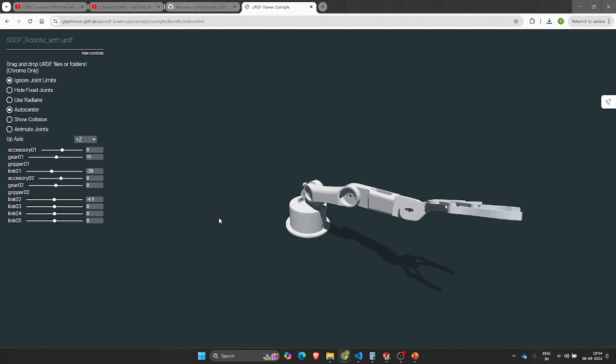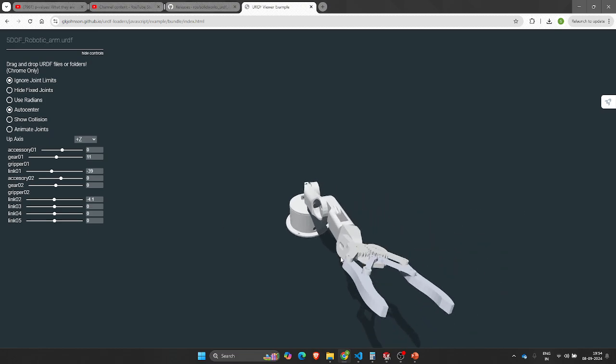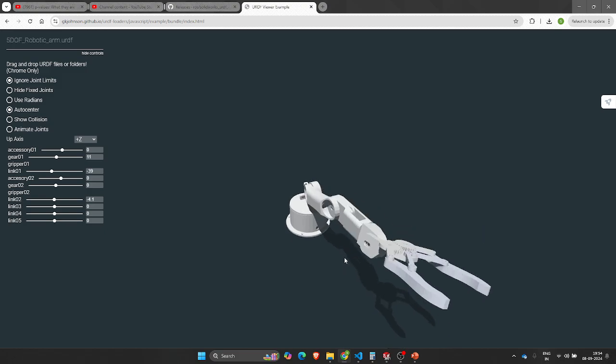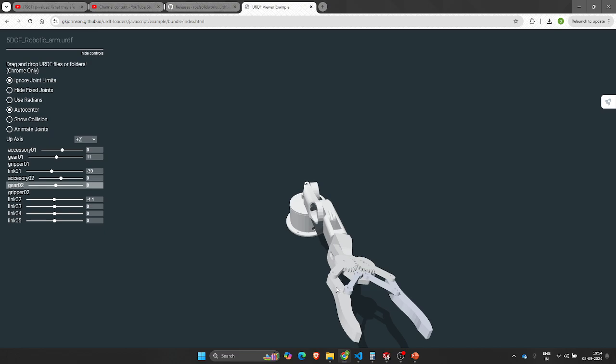But if you have understood and seen how I debugged the issue, and if you are building your own CAD model, coming up with the URDF and want to integrate it in a ROS2 environment, I guess this would act as a base tutorial for how we could do that. There are a few errors here, as you could see that we have not set proper joint limits for each revolute joint. We would see that in the upcoming class, as in how we set the joint limits in a URDF file.